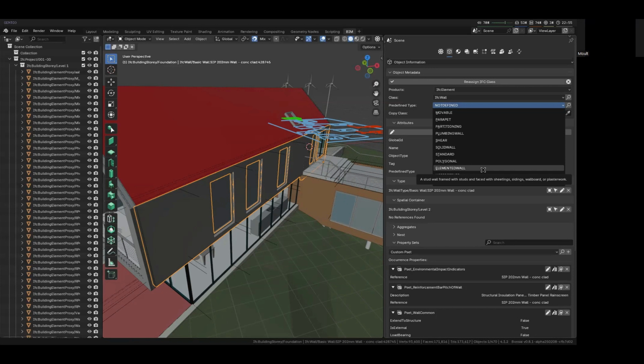So it's now being removed. You should not use it because a standard case wall is identical to an object which has material layers assigned to it. A polygonal wall is equivalent to a wall which doesn't. An elemented wall is equivalent to an aggregate of sub objects, like members and coverings, that make up a wall.